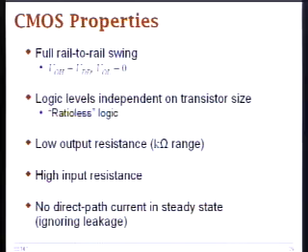You notice that in steady state, logic levels are independent of transistor size. No matter how strong your transistor is, after all the transients settle, you will have one of the transistors pulling down or pulling up while the other is turned off. And there you will have clearly defined logic 0 and logic 1.